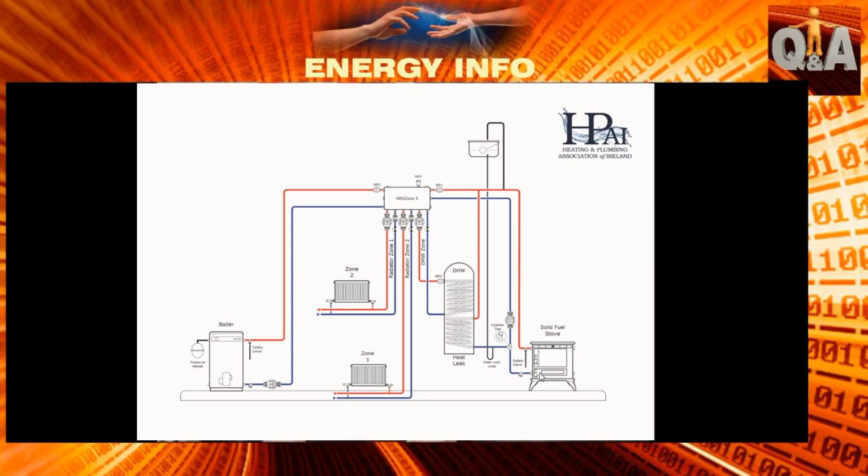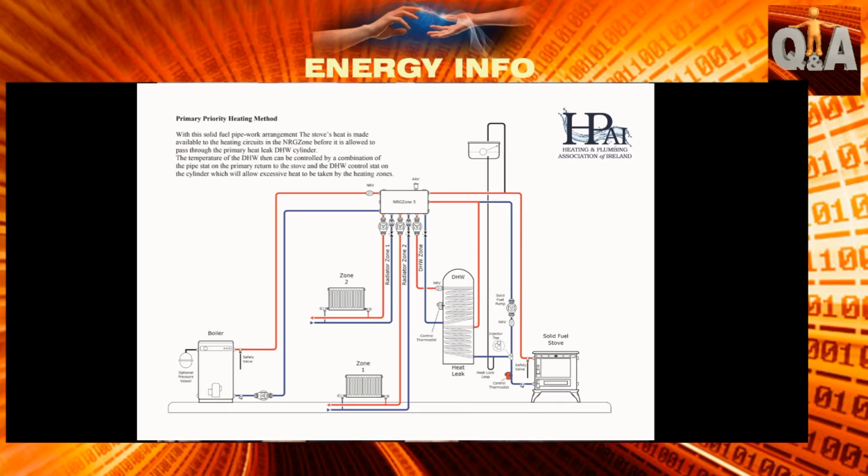Now this is just the same type of system, except it's hot water, it's central heating priority. Forgetting the fact that it's a manifold, if it's motorised valves or whatever, the flow goes towards the distribution system first, and when that is satisfied, there's a bypass within the energy zone manifold, as with other manifolds, and when it goes to that, then it passes the cylinder flow and drops down.